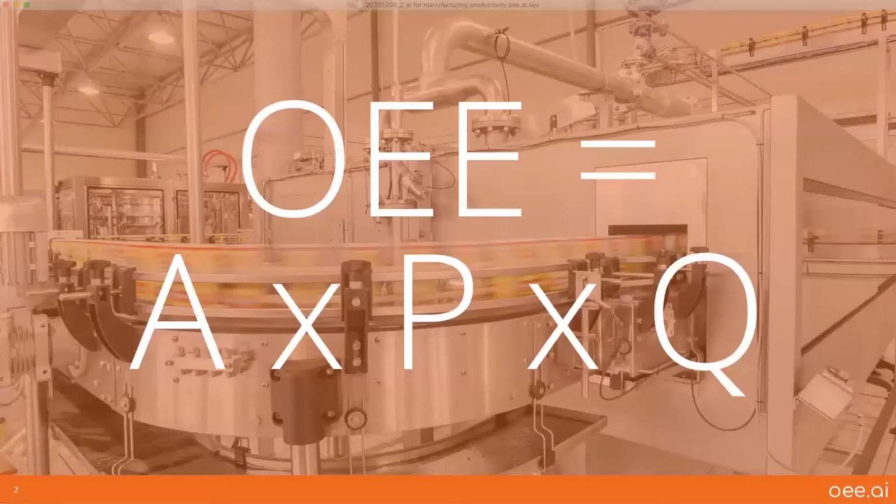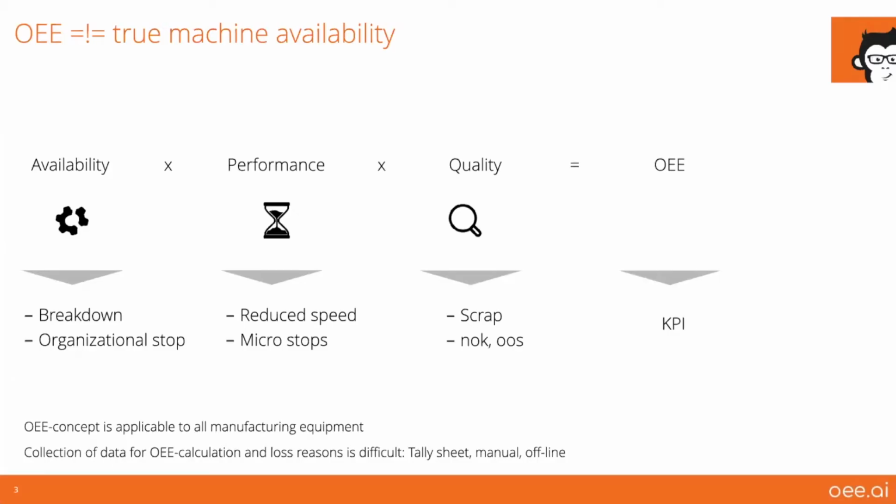The OEE is the overall equipment effectiveness, and that's the true machine availability. And it comprises of availability losses, performance losses, and quality losses. That means that the OEE itself is a KPI that shows how good your machines are running. And if you know that the machine has some certain problems, it also shows you where the problem is, which means that the availability shows you how much of the planned time the machine is running and has standstills, like classical breakdowns, changeovers, missing personnel or something. That is when the machine is really stopping.